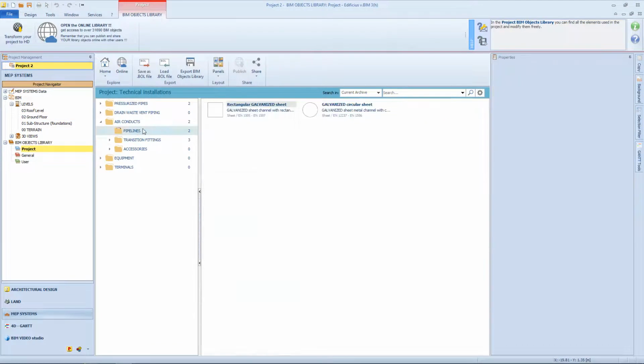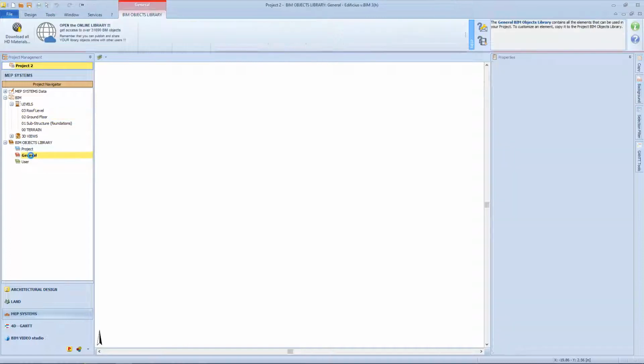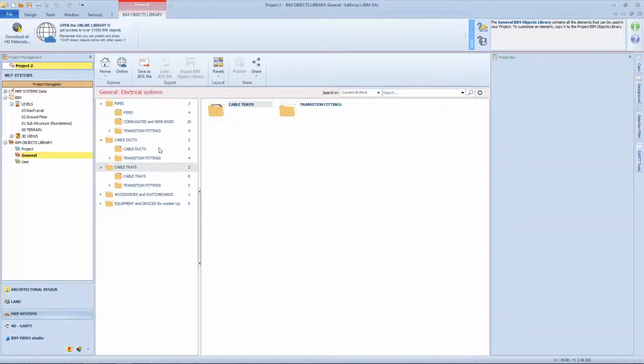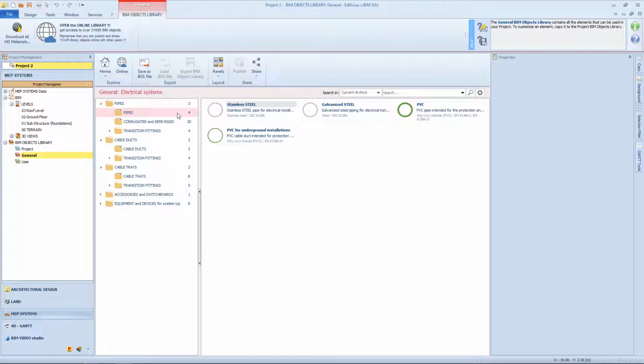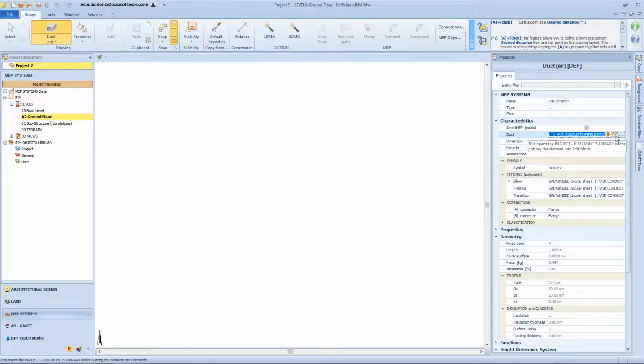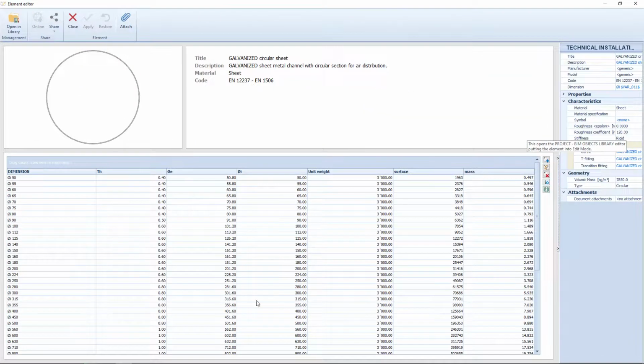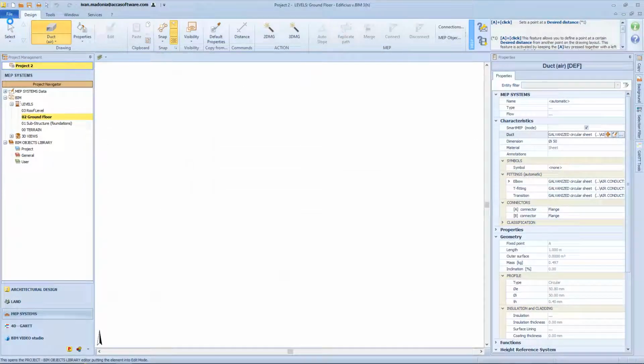After choosing the material and shape for the pipe profile, remember that you can always access the library and customize it. The libraries can be accessed from the Navigator by reaching the relative folder in the mechanical or electrical systems and opening the editor relating to the library to be customized. By clicking on the pipe or pipe field from the Properties toolbox, then on the Central button, you can access directly the editor of the relevant library in the Project Library.